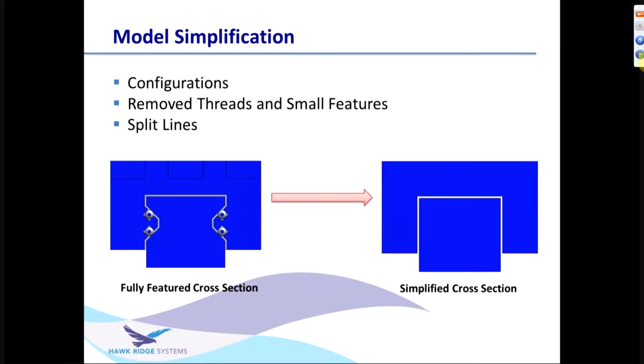I encourage you to do the same when working with your own parts and assemblies, because it allows you to switch back and forth more easily between what you would create in real life versus what you would use in a simulation. And to take things further, it's good to create simplified configurations at each level. To show you, let me switch back over to SOLIDWORKS here.